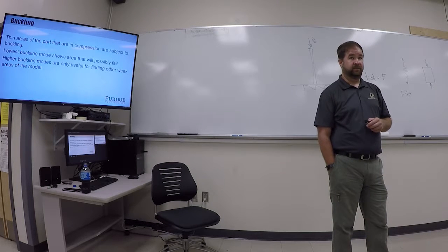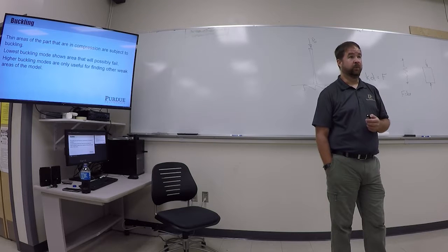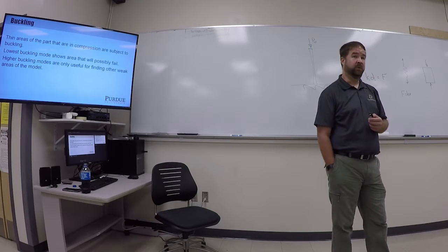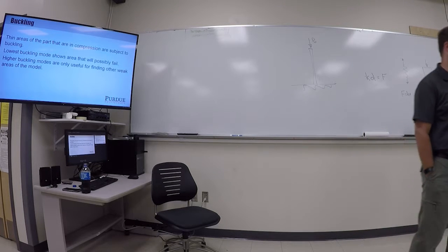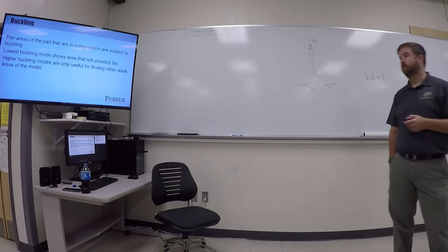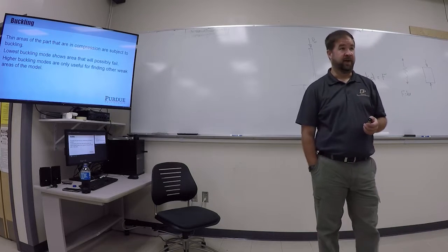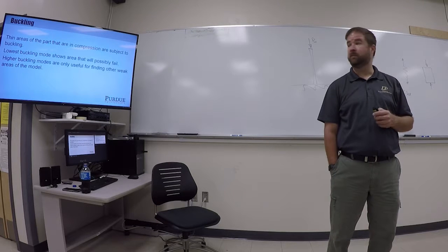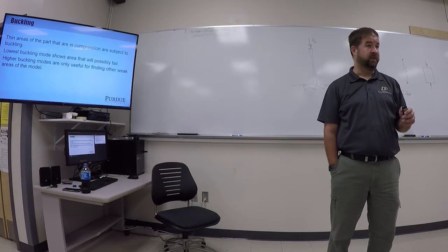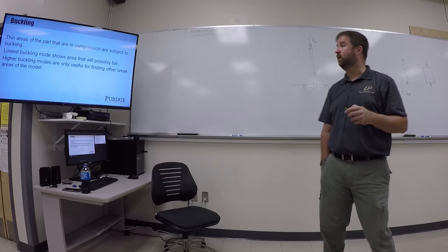Obviously, the reality is if we did design it for that, then we're designing it for something that maybe would happen only occasionally, but you're going to have to pay the penalty that every car is going to be more expensive because you've designed for that. Okay? Probably a much cheaper way to do that is to put some pressure relief valves in it or something that would allow that vacuum to be released if it was ever inadvertently created.